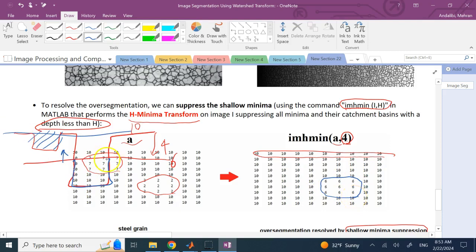Now what happens is that the region of 7 is gone, and this region of 2 is not going to be 2 anymore, because when I fill that, I brought down my baseline by 4. So now everything is measured from this new blue line. Therefore, this depth that was once 10 minus 2, which is 8, is now 4, which we went down, plus what it was, 2, right? So it's equal to 6 now.